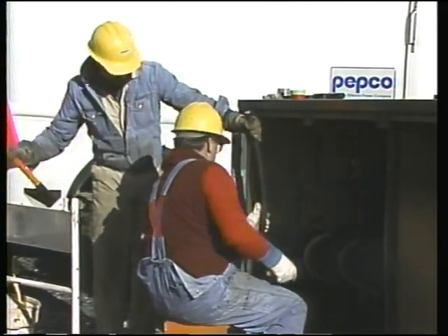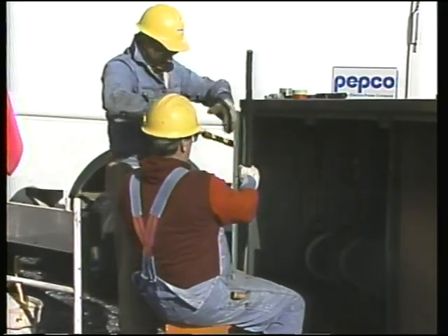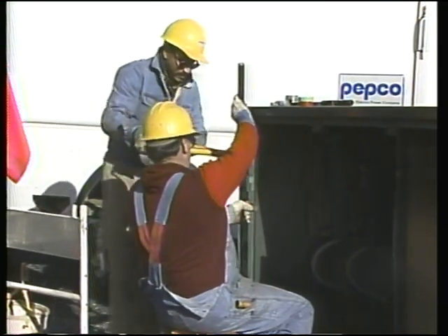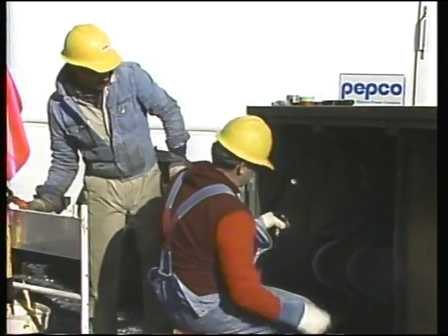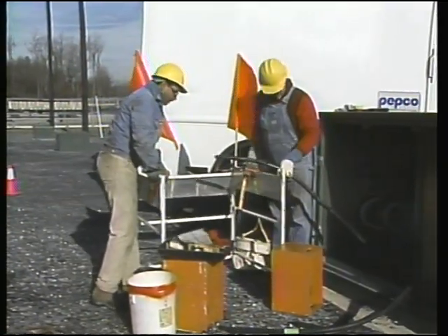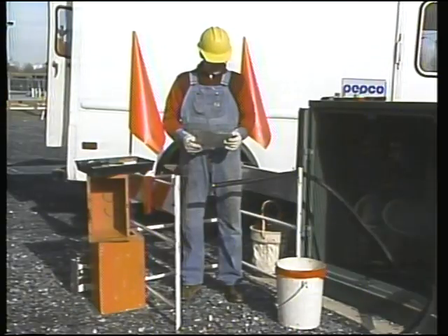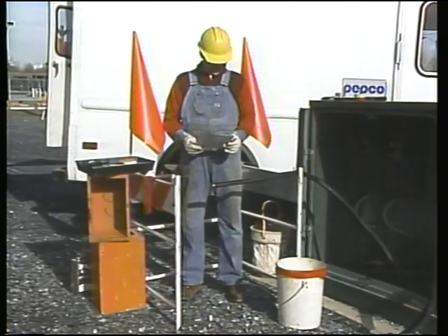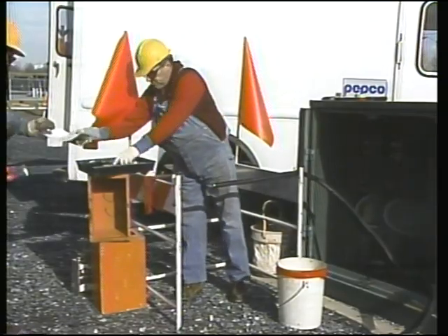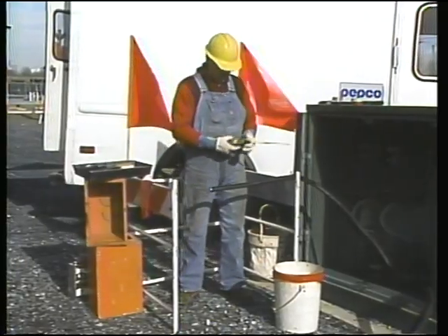When this cable was installed, enough slack was left so that it could be properly trained after the termination is made. One of the first steps in making the termination is cutting the cable to its specified length. After the cable has been cut, it's secured so that the cable end can be prepared. Preparing a cable involves removing the various cable layers according to a specific set of instructions. Following these instructions is essential to ensuring that the termination is made correctly.